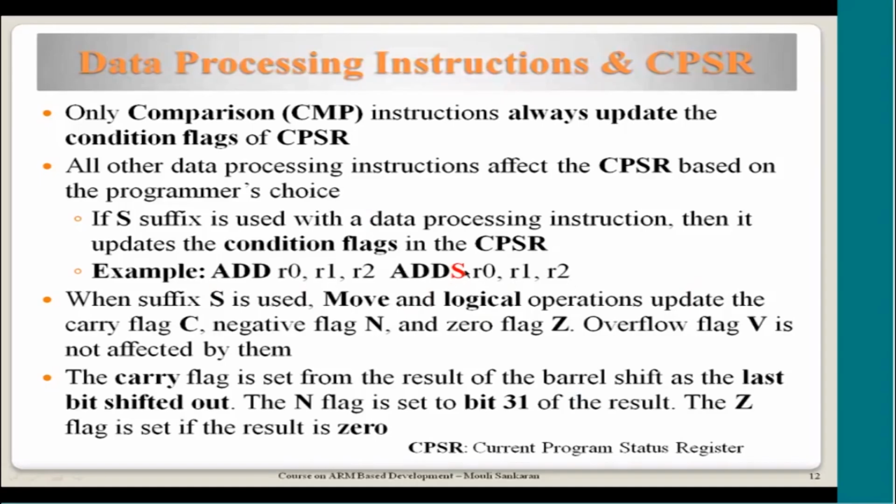Along with this, if you say ADDEQS, then the execution itself will be based on the value of the current CPSR, and then if it is allowed to get executed, whether it can impact the flags or not. So these two are different conditions. For a particular instruction, both can be mentioned.